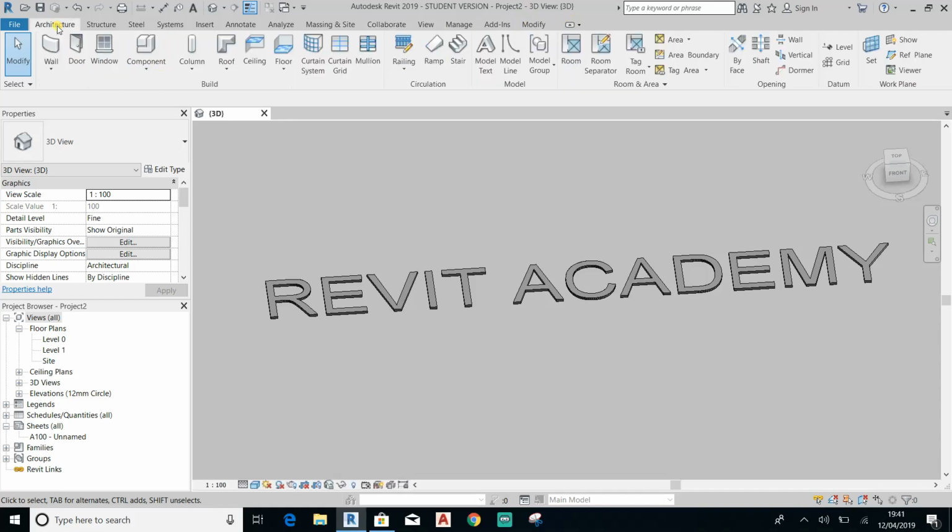And today's session is going to be about the user interface of Revit itself. The Architectural tab: all 3D models, all 3D geometry within the model comes from here. So if you want to create a wall, door, put windows into the walls, floors, ceilings, roof, create a curtain wall system, it all comes from this tab here.